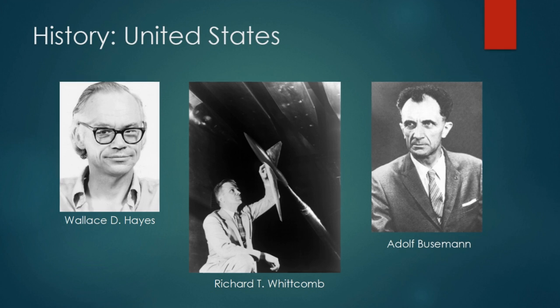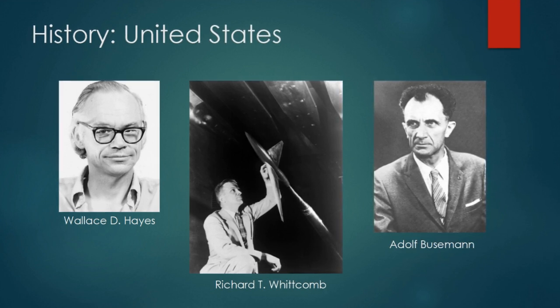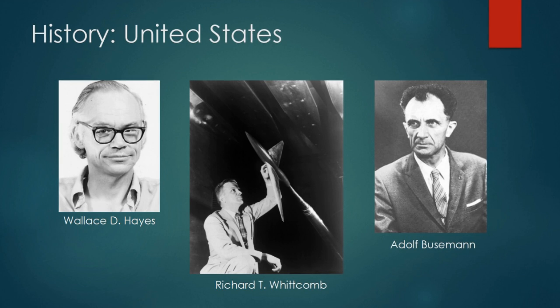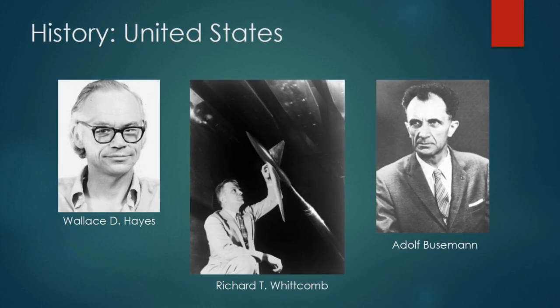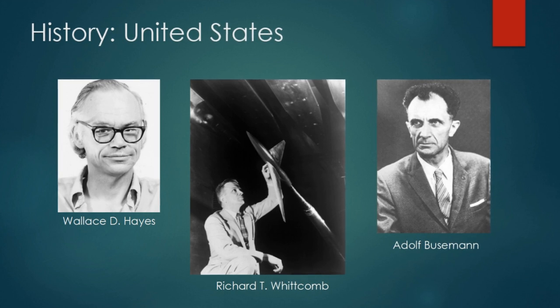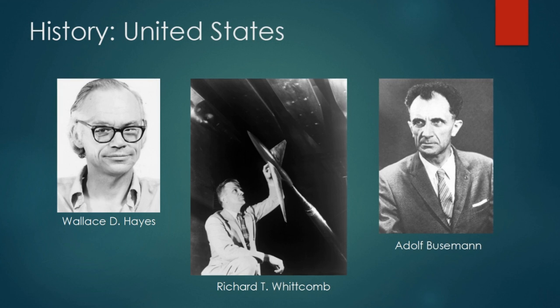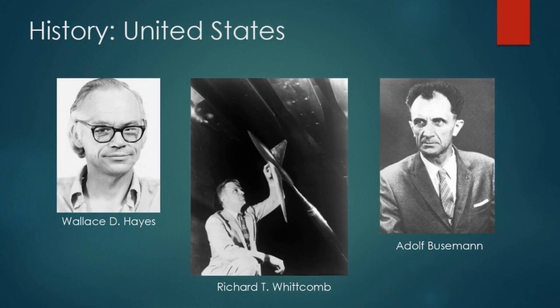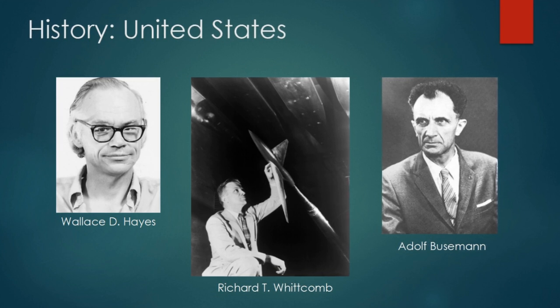While using the new 8-foot high speed tunnel, a wind tunnel with performance up to Mach 0.95 at NACA's Langley Research Center, he was surprised by the increase in drag due to shockwave formation. Whitcomb realized that for analytical purposes, an airplane could be reduced to a streamlined body of revolution, elongated as much as possible to mitigate abrupt discontinuities, and hence equally abrupt drag rise.